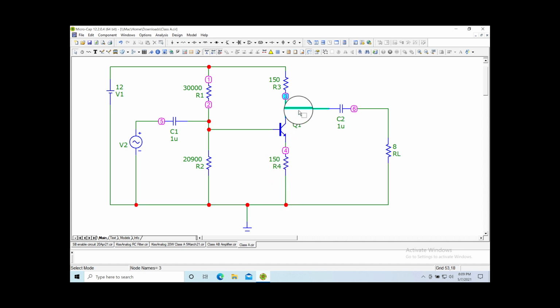Well, that's a parallel path, right? Little current would go this way, 150 ohms, 150 ohms, 75 ohms in parallel. So 75 ohms source impedance driving an 8 ohm load. That's not very good. That's kind of the opposite of what you want. You really want your source impedance about 10 times less than your load. So you really want this down to, say, 1 ohm or 0.8 ohms. So these guys look like they're too high a value.